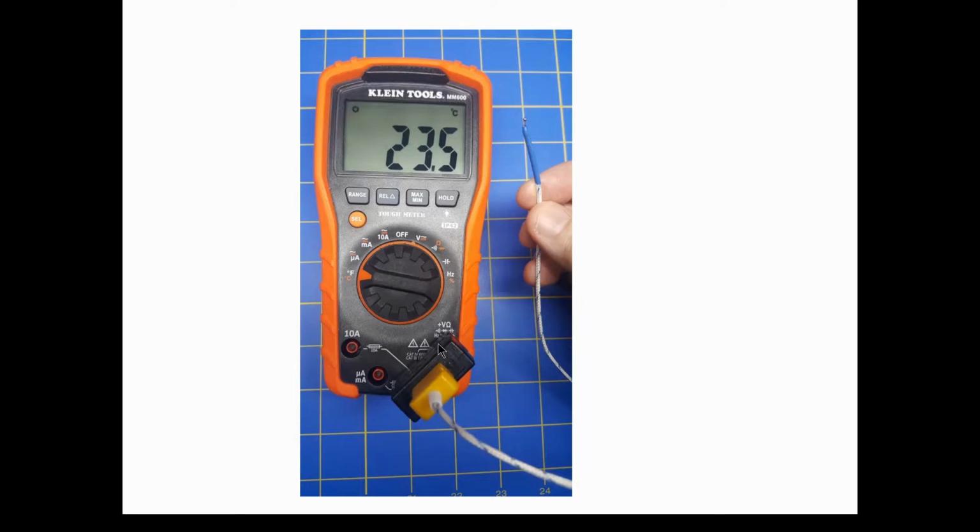If you have a multimeter, it probably came with what's called a thermocouple, which is a temperature measurement device, and it looks just like this. It's got a little bead at the end, and it uses that bead. You put it against the case of whatever you want, of course, making sure you're safe and you don't hurt yourself. You put it against the case and it will measure the temperature. And you can see right here, it's out in free air and it's measuring 23 degrees centigrade, which is about 73 degrees Fahrenheit. But you can use this device to actually measure, in the real world, actual temperatures of stuff.